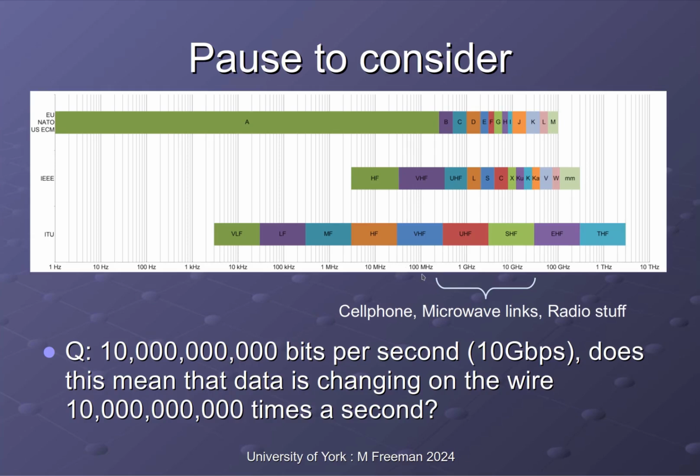Now, if you increase the frequency, those higher frequencies will be attenuated more severely, so your cable runs will have to be shorter. So if you look at your 100 megabit, gigabit and 10 gigabit, you'll typically see that your cable lengths are limited to 100 meters or less. And the higher the bit rate, you have to start to use more exotic cables with increased levels of screening. And equally, the electronics that you'll need to receive that data needs to be more specialized, as the data you put on at one end of the cable at the transmitting end will not look the same as it gets to the receiving end. It will be severely attenuated. However, as long as you can differentiate between the different voltage states, then that's perfectly fine. So yeah, as we go up to higher data rates, our frequency components within the wires do increase, but there is a limit.